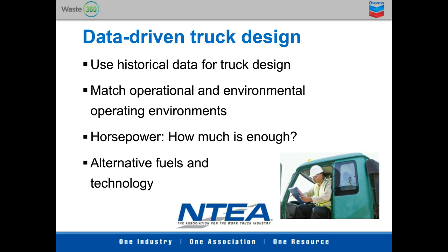One of the easiest things to do is look at powertrain optimization. Again, going back to that drive cycle: what is our maximum cruising speed? What's our required starting gradeability? What does this thing need to do? And all that can be charted and go into your vehicle design.